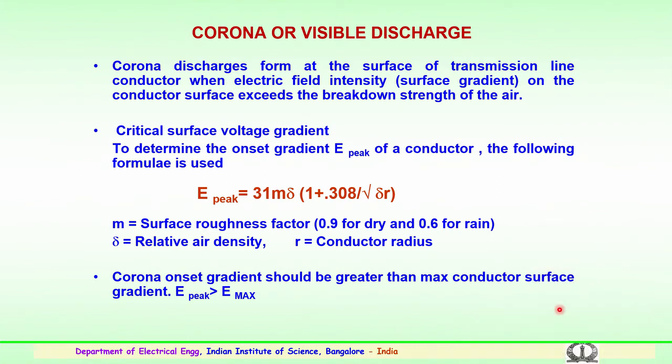So, further, the conductor which is to be used for the EHV or UHV transmission is very important. It has to be seen that discharges like the corona or visible discharges should not be generated on the surface. This again will create problems for communication, or power loss because of the conductor.